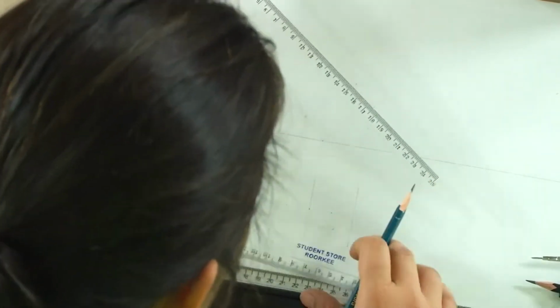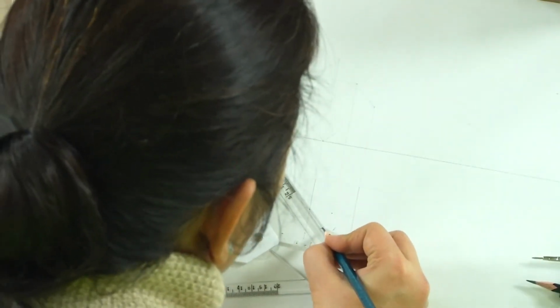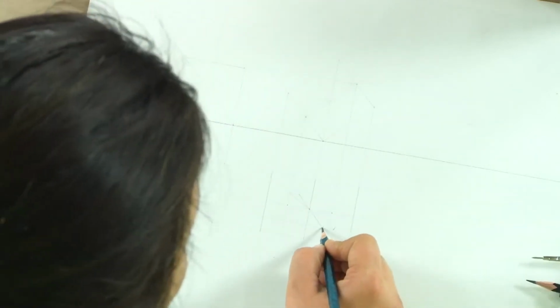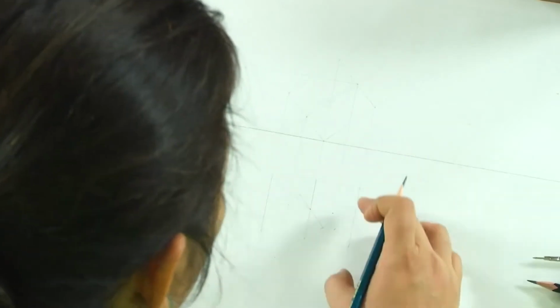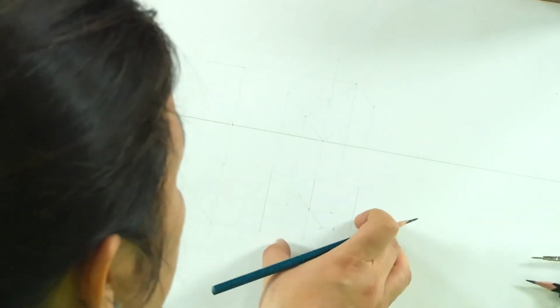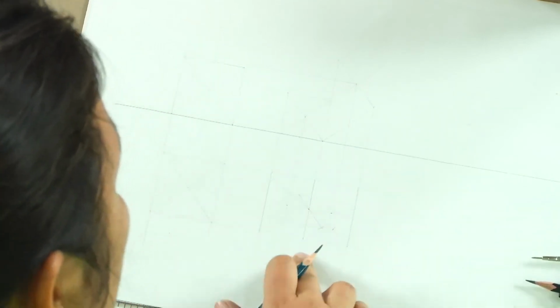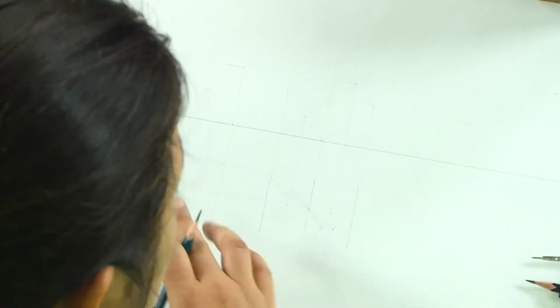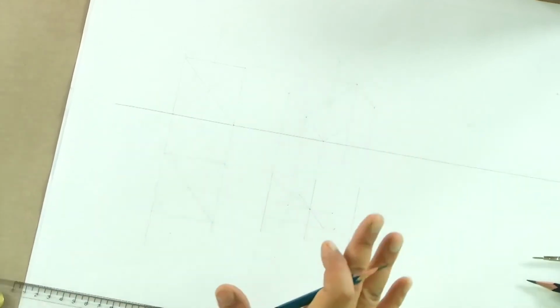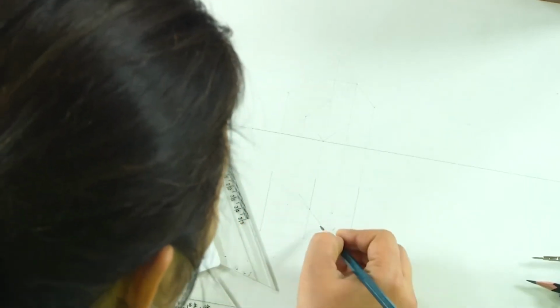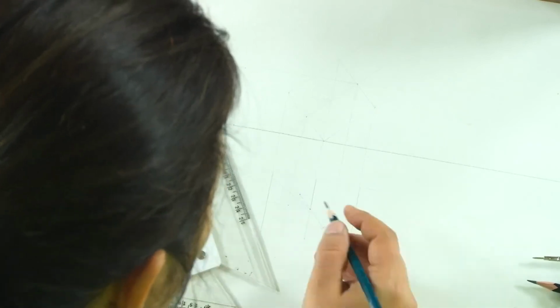So what we actually have is an axis passing through this point and having its trace there. So we have this entire cube rotated in such a manner that this axis now occupies this position. The rest of the drawing will move about this axis, and we will get a cube which is rotated in such a manner that the axis makes an angle of 30 degrees with the VP. So this is the revised axis, which is what we have got.